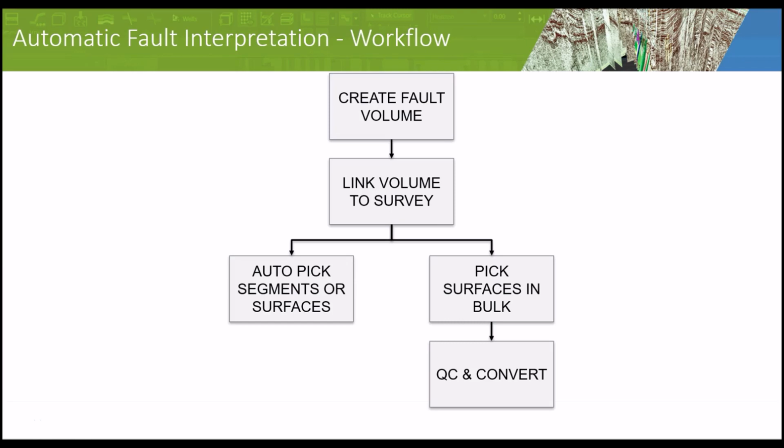So this was an overview of the new automatic fault interpretation workflows that are coming out this summer. You can auto-pick segments or create fault surfaces and add them to the interpretation. You can also run a bulk picker to batch create fault surfaces from your fault volume. We have some productivity and analysis tools like the rows diagram, interactive merging and deleting to help you analyze all the faults in your interpretation, temporary or otherwise, and this will hopefully help speed up your fault interpretation process.